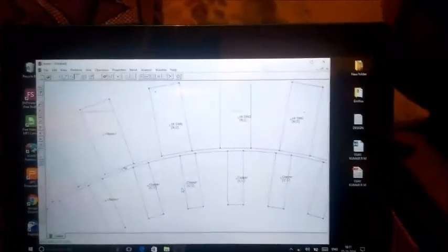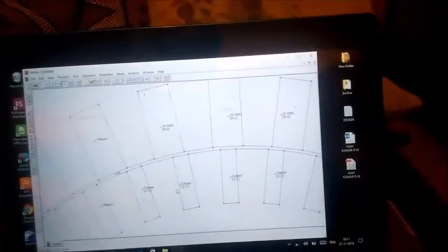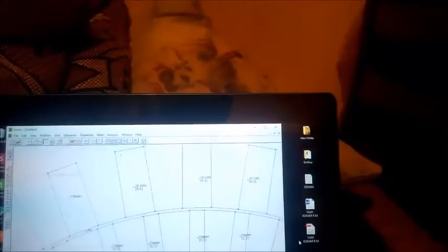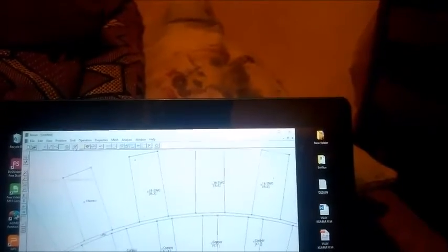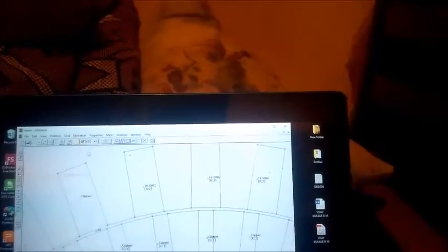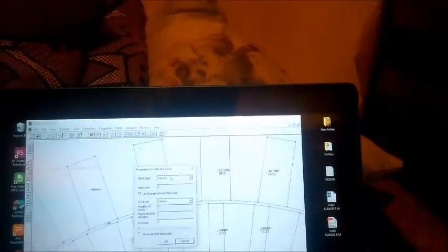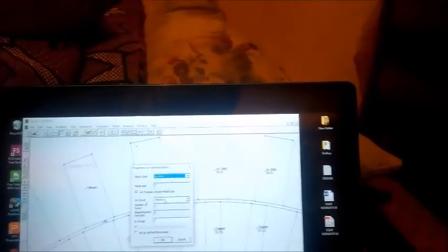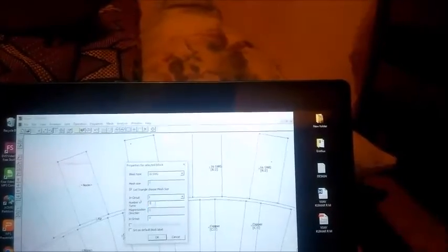I need to mention another important thing: you can repeat this sequence once R is over, Y and B. So next this will constitute a north pole. Now you need to have a south pole also. For the south pole, the same procedure, but in turns you just choose it. In turns, I'm just showing, let it be Y. So here instead of 1 just make it -2.